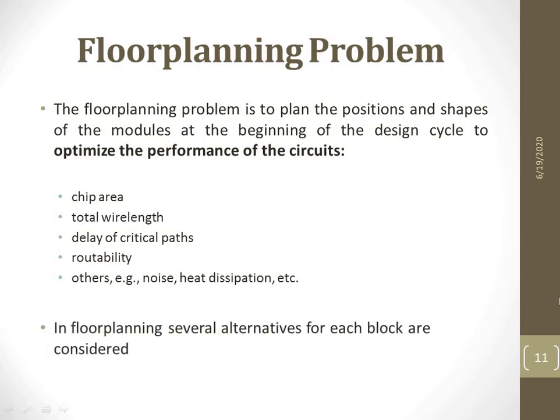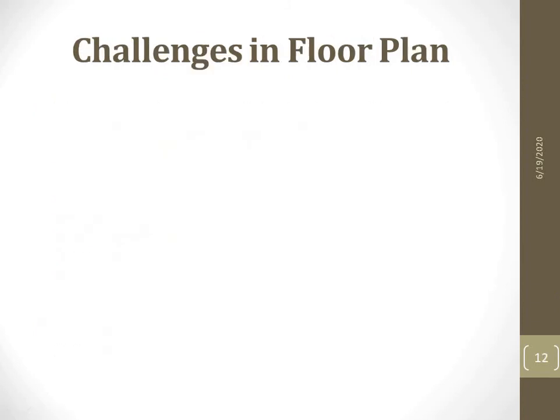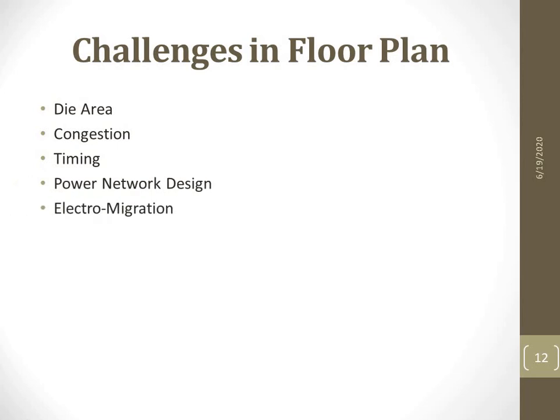In floor planning, several alternatives for each block are considered. They are to be considered, without which we cannot make it perfect. Challenges. What are the challenges in floor planning? The challenges are, as I said, chip area or die area, congestion, timing, power network design, electromigration, and IR drop. So what are these?